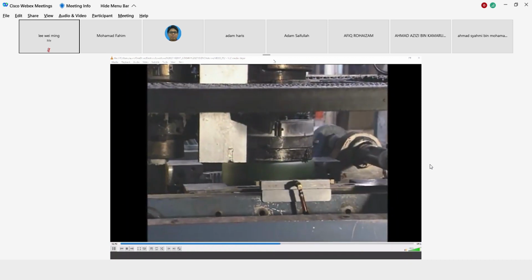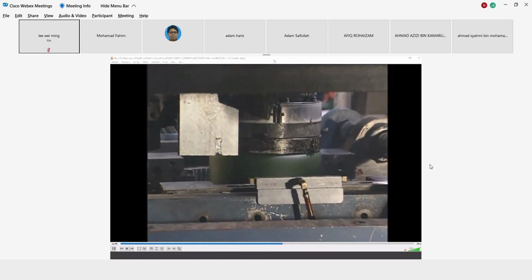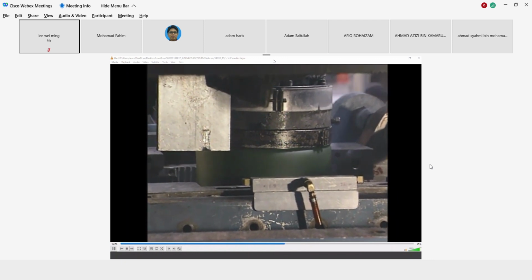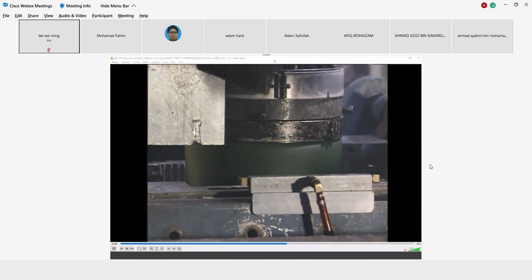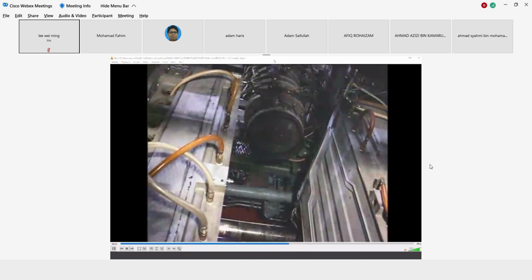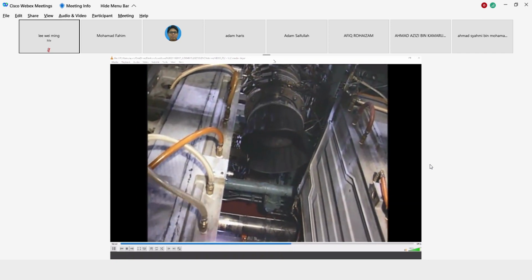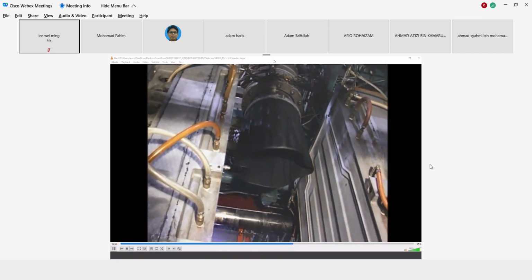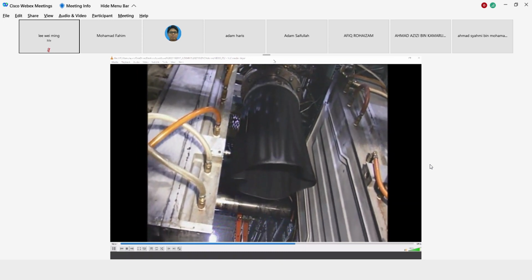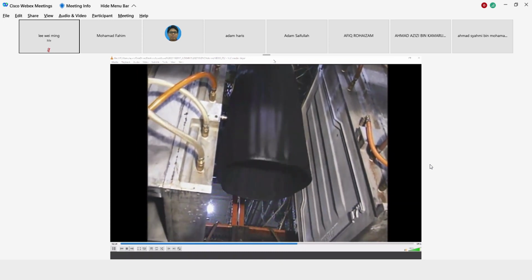The process of extrusion blow molding involves applying heat and pressure to thermoplastic resin to produce what is called the melt. This melt is then forced through a die to produce a parison, which is then dropped, trapped, or conveyed to an open blow mold for subsequent blow molding.